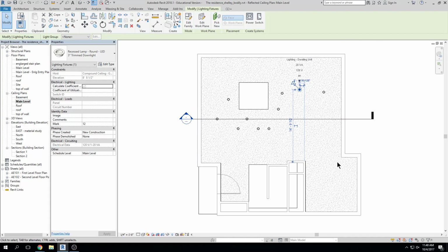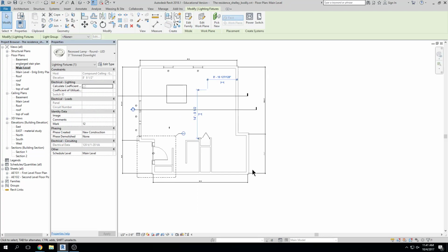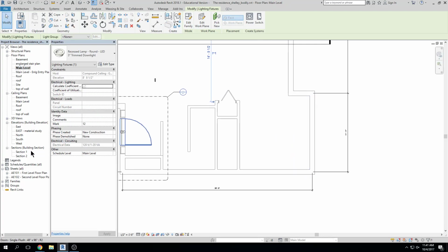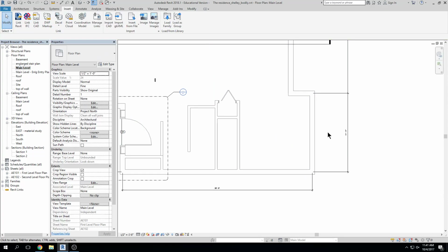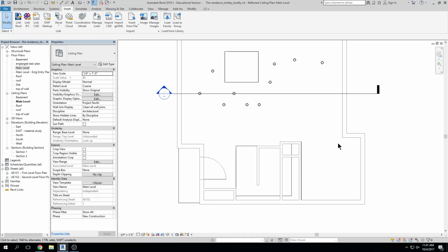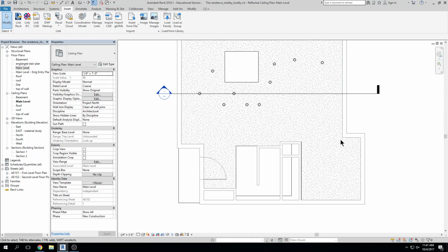So let's say we want to, this is the kitchen, if I remember. Let's look at my view range and make sure. Do we have any windows? I don't have any windows. We'll just drop some soffits there. Okay, so I'm going to drop a portion of the ceiling right here down a foot, okay?